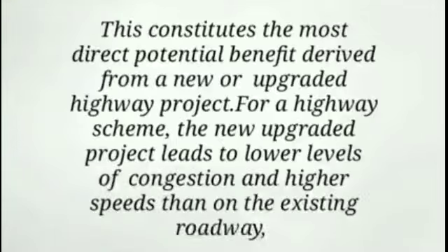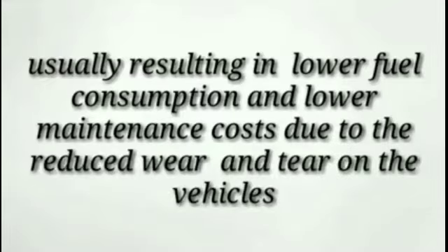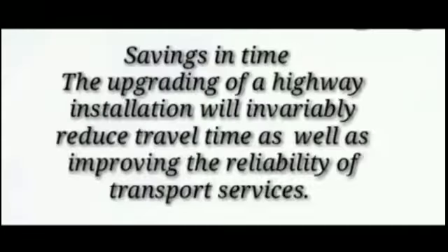Reductions in vehicle operating costs. For a highway scheme, the new upgraded project leads to lower levels of congestion and higher speeds than on the existing roadway, usually resulting in lower fuel consumption and lower maintenance costs due to the reduced wear and tear on the vehicles. Savings in time.